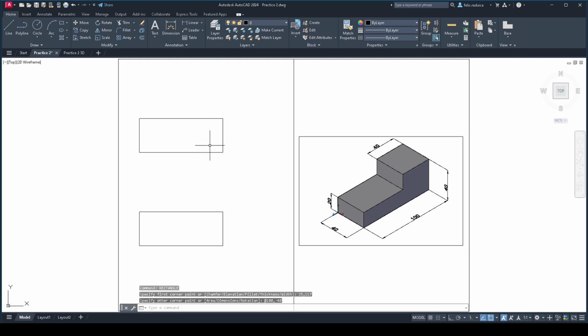Now I only need one more rectangle, which will be the side projection view. We will use the same y coordinate as here, so 227, but the x coordinate will be 1a plus the length plus another a, so that makes it 150. So give the rectangle command and the first coordinate will be 150 and the next one will be 227.